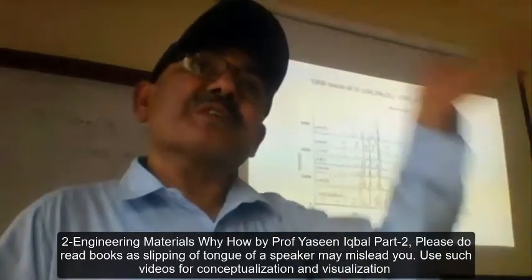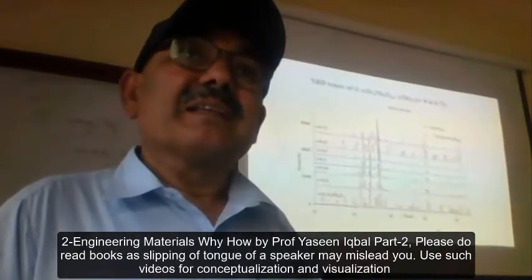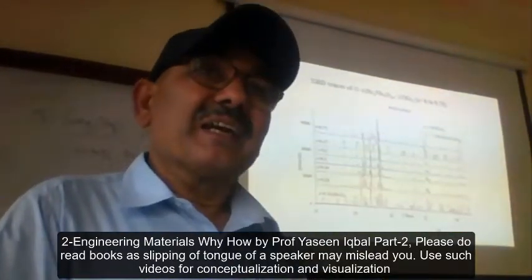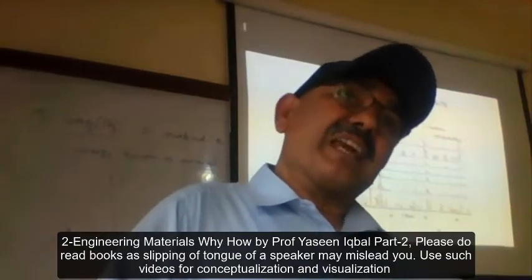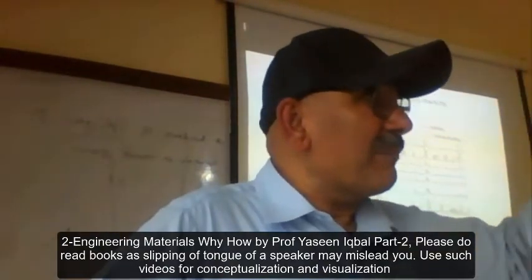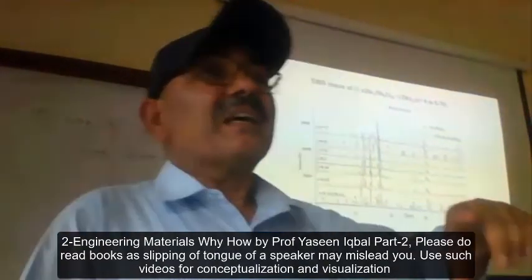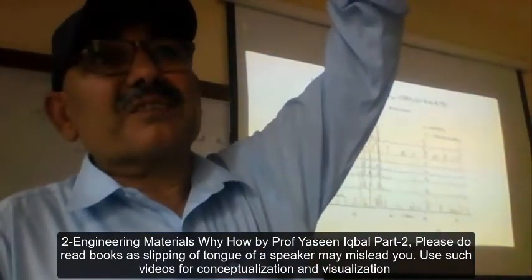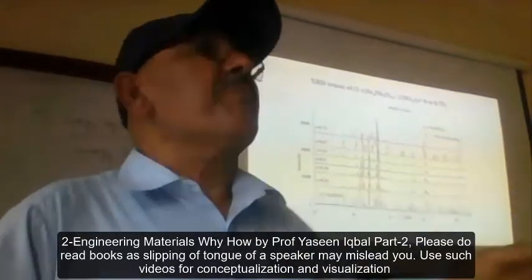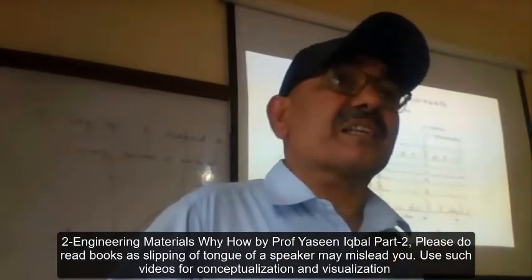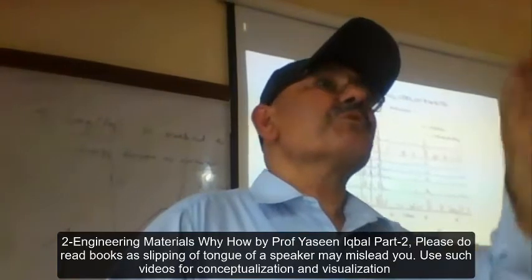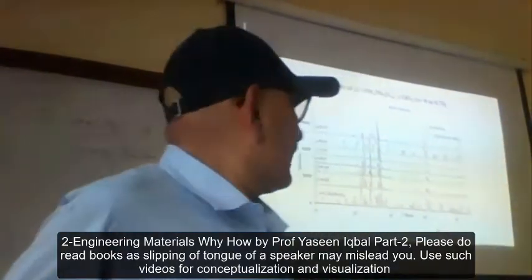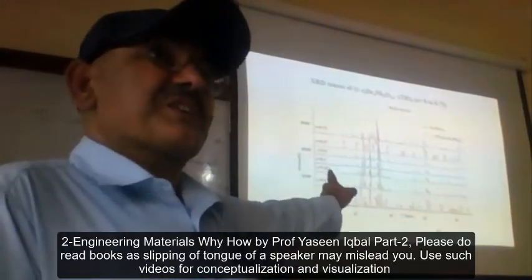But if the composition is different, the element is different, the quantity is the same but the elemental cation is different, then some cation will give me brighter contrast in backscattered imaging. Backscattered imaging is basically composition contrast.